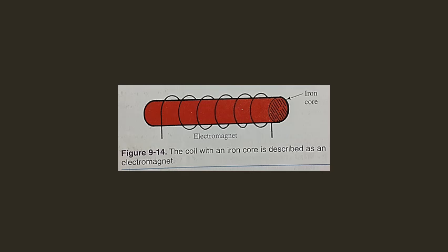If the depowered magnet is brought near some iron filings, the filings will be attracted to the core because the iron core has retained a small amount of its magnetism. This magnetism is called residual magnetism. If very little magnetism remains, the core would be considered as having low retentivity. Retentivity, then, is the ability of a material to retain magnetism after the magnetizing field has been removed. If a core retains a good deal of magnetism, it is said to have high retentivity. A soft iron core shows low retentivity. A steel core has high retentivity.